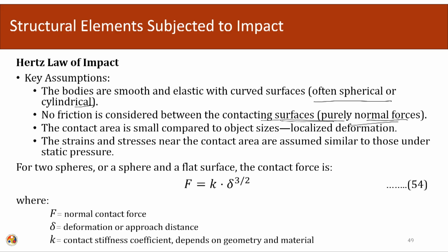The contact area is small compared to the object size. The contact area between the impacting bodies is assumed to be small, which means that we are looking into localized deformation. The strains and the stresses near the contact area are assumed similar to those under static pressure.